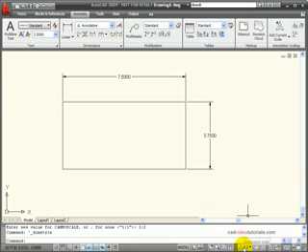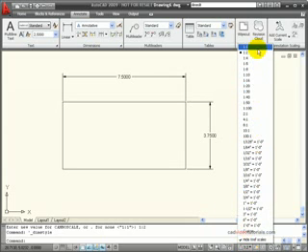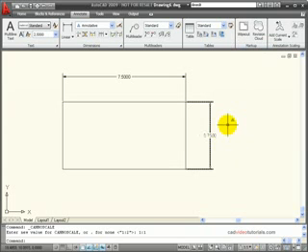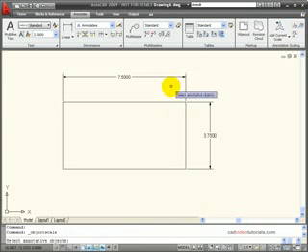Down here on the status bar I have my annotation scale for model space, and even though I change the scale, you notice that the size doesn't change. That's because unless the scale is added to my scale list, these objects are not going to change to that other scale. To find my scale list, I'll go to the Annotate tab, and on my Annotation Scaling I can look at my Add and Delete Scales box.